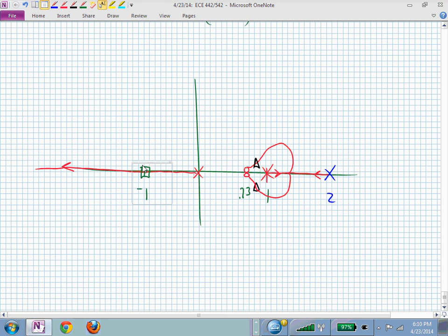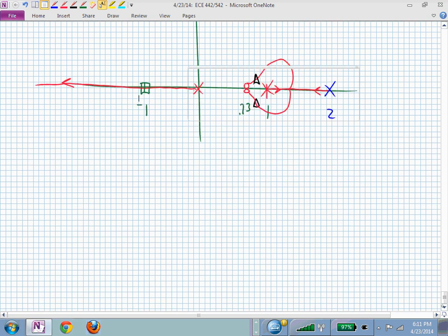And then we're hoping that maybe that might have been bigger. So where would our other squares be? They would be closer to those zeros than the triangles, if that square was going to make our third triangle be inside the unit circle. So let's check our gain at the square.